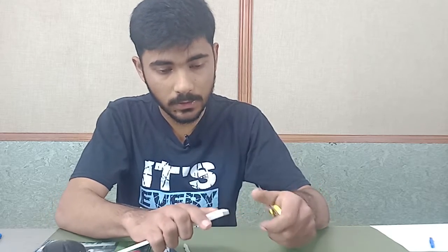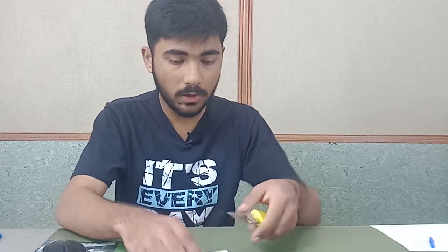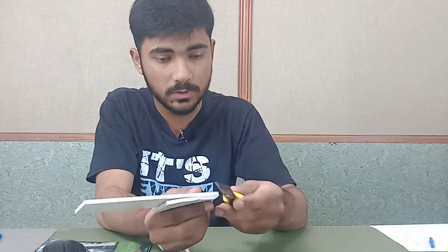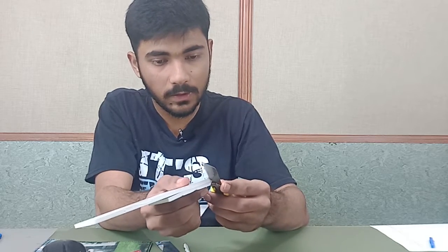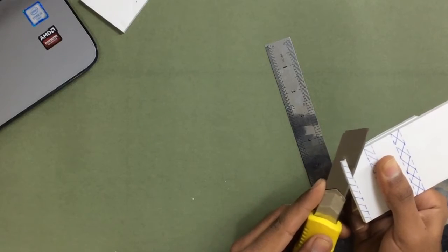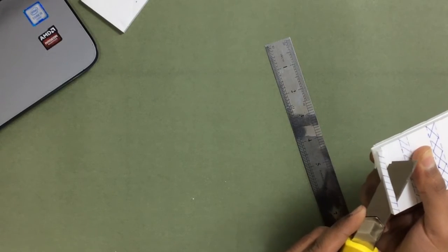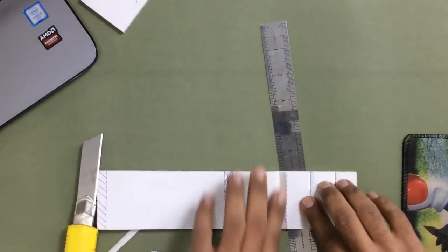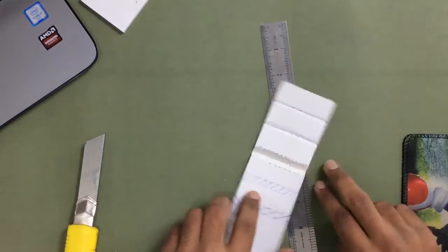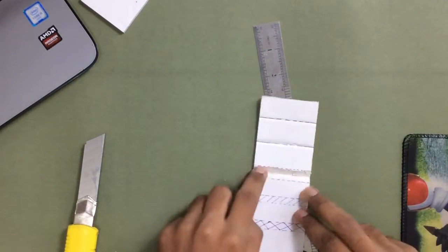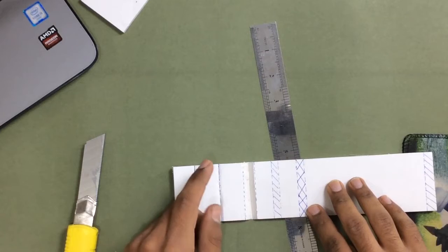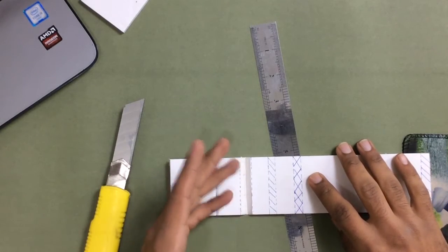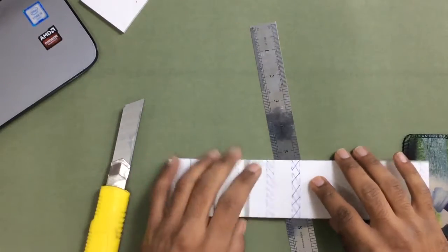I can do it better when I put this foam board on a table side, but right now I'm just holding this one in my hand. So now we have got a 45-degree bevel, and you can just bend it like this. You can use that one in your elevons or aileron hinges, so that will work better.